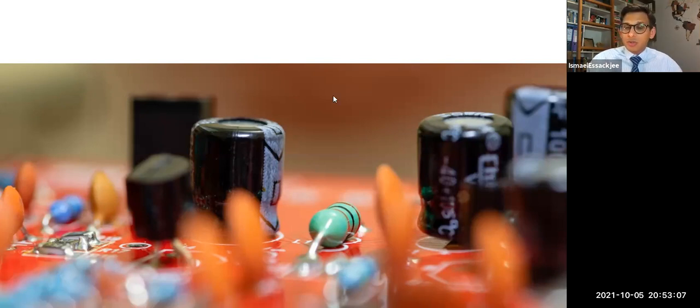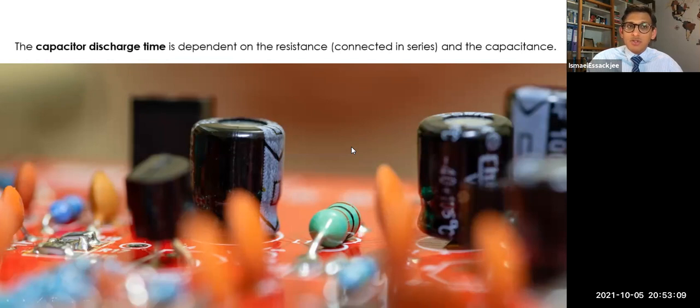Just be careful when you're working with higher voltage. The capacitor discharge time is dependent on the resistance, which is usually connected in series, and the capacitance. The bigger the capacitance, the more charge it can store, so you will need to give it time to discharge. Be very careful about all these things.